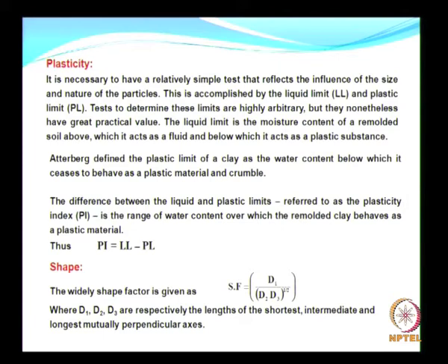So what is plasticity index? Plasticity index is the range of water content over which the remolded clay behaves as a plastic material. Thus, plasticity index is the difference between the liquid limit and the plastic limit.